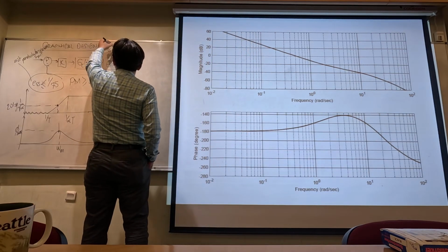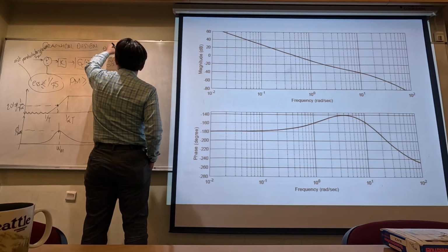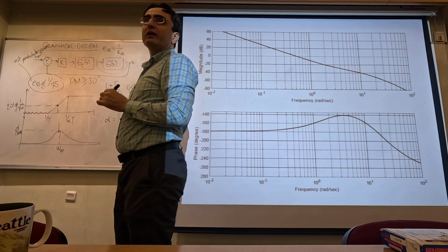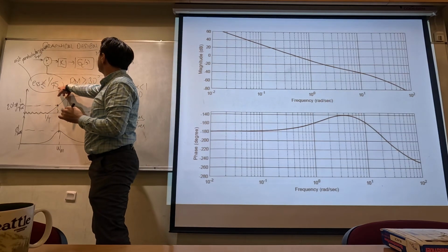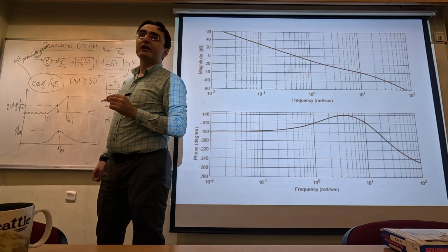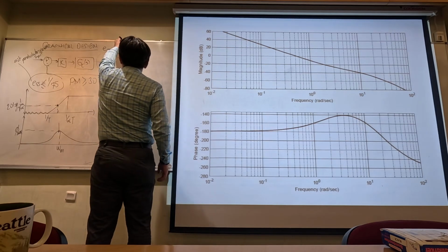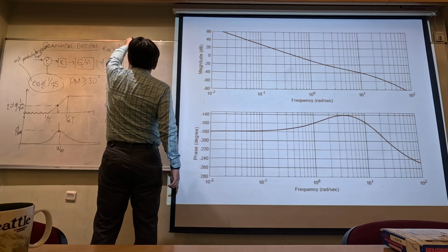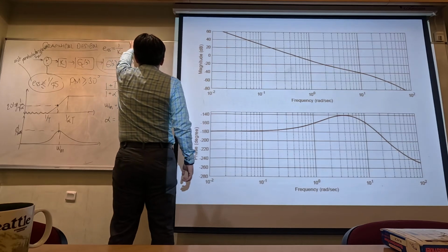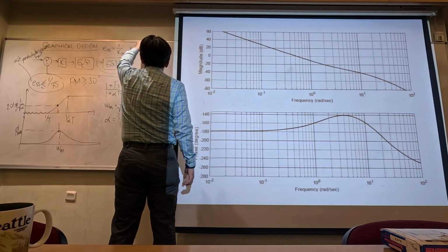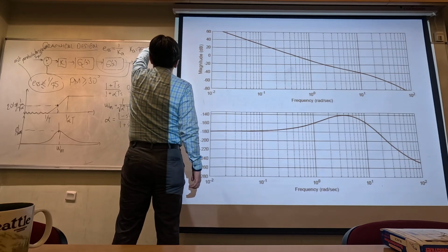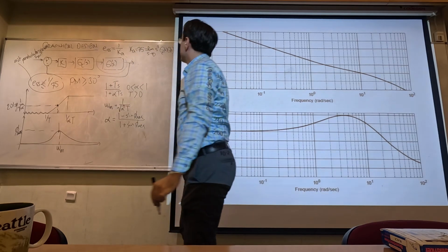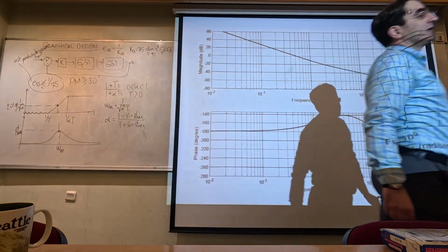We know that the steady state error for unit parabola input is 1 over Ka. If I want this number to be 1 over 75, what should be Ka? Ka is going to be 75, okay? And I know that Ka is defined as the limit as s goes to 0 of s squared, Gc of s, and G of s. That is what Ka is.